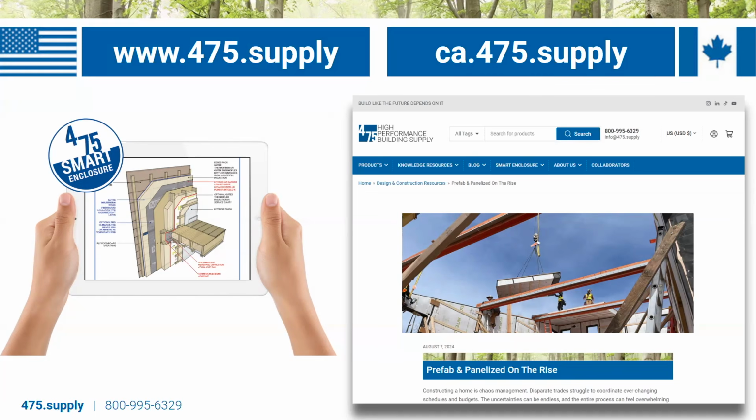So we're oftentimes bouncing assembly details back and forth with designers, helping talk through different options, helping select the proper water resistant barrier, helping select the proper interior air barrier. And then we're doing a similar conversation with the builders, oftentimes highlighting sequencing concerns. Let's make sure to place this interior air barrier before we run the top plates for our partition walls, for example. Or let's remember to cover the rim joist with a piece of tape for our air barrier transition around a floor system. We can also help the contractors with their estimates and pricing, and then talking through things on site or helping with quality control.